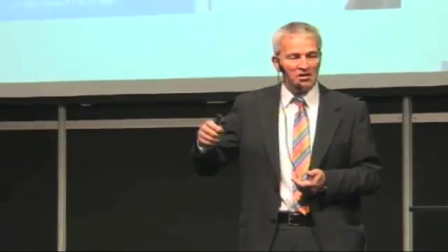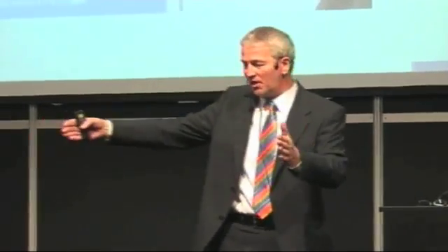On an open machine, can you imagine a drill and a swarf which is going around a diameter of half a meter or more? It will not just cut a little bit your finger. It will cut off your ear or the nose, and we shouldn't accept this. So chip control is a basic challenge.